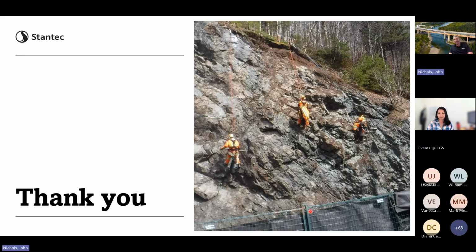Yeah, okay. So I kind of hinted at that. That would be an anisotropic material, not an isotropic material, right? A shaly, if my understanding is correct, like a shale. So the first thing I would do is see, kinematically, if you have daylighting. And daylighting would simply mean, the dominant feature in shales would be that schistosity, right? If the shaliness of it is dipping out and daylighting, then you would look at the strength of the actual plane itself, which is relatively weak in a shale.